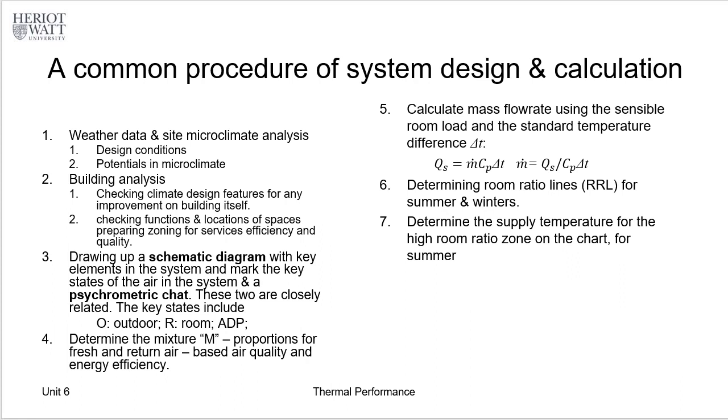From here, we can find out the moisture content through the calculation or through the psychrometric chart. Here, if we do it by psychrometric chart, we need to determine the room ratio line. And then through the psychrometric chart, we can determine the supply air moisture.